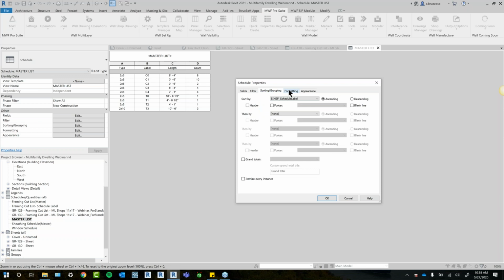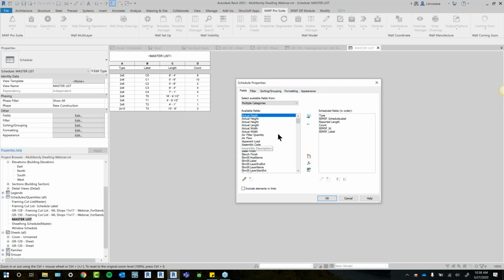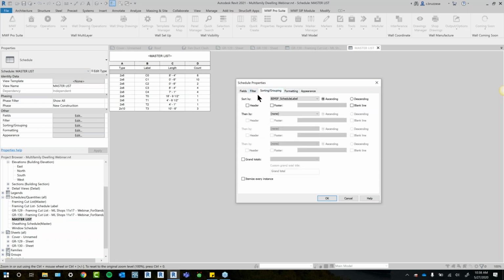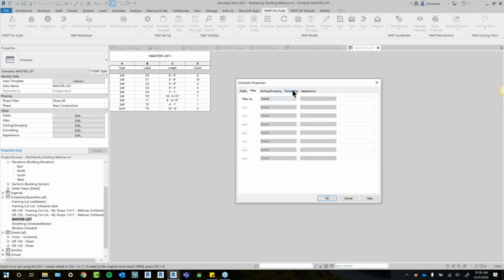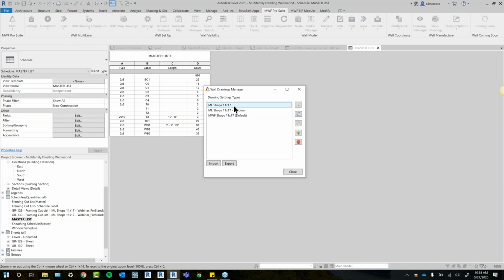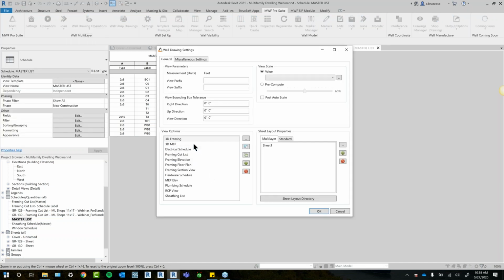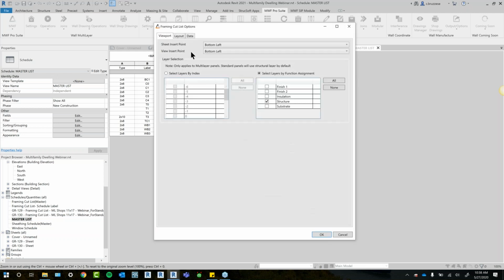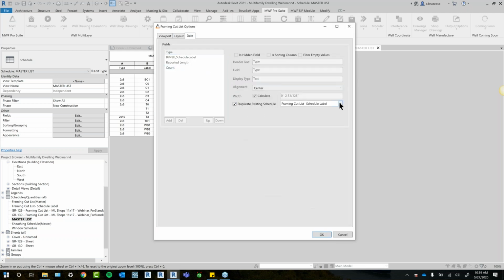And this will make it a general Revit schedule that you can then use to duplicate. It just saves you the hassle of having to add in the fields and get your sorting figured out. So this is something that you could always reuse over here. And we can always go ahead and duplicate this guy for every single shop drawing.